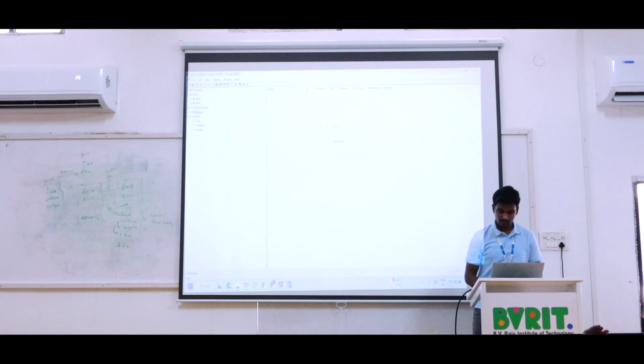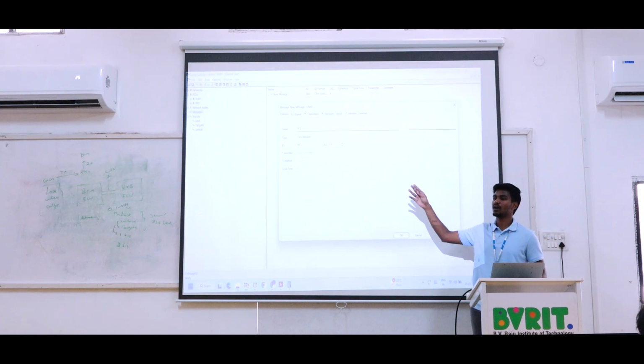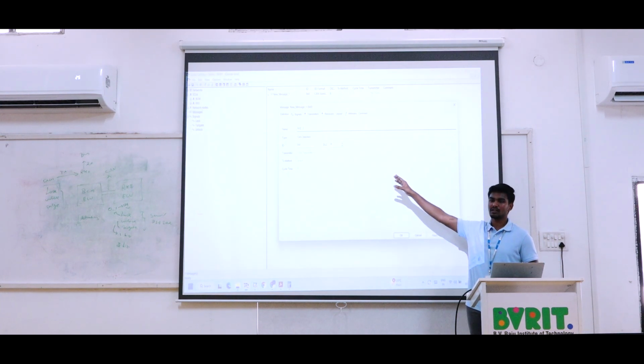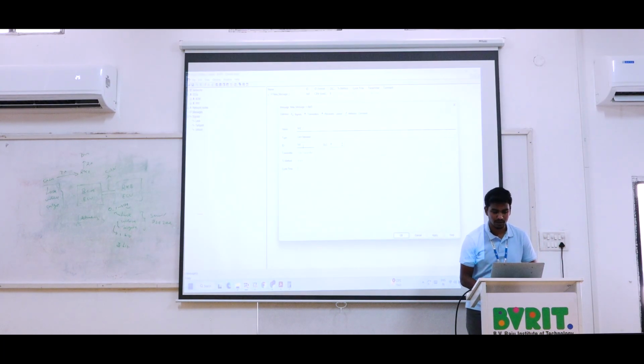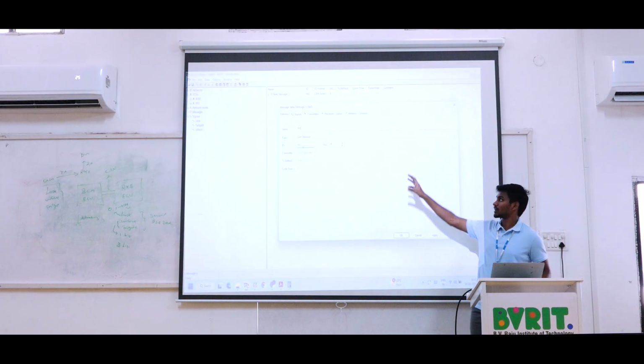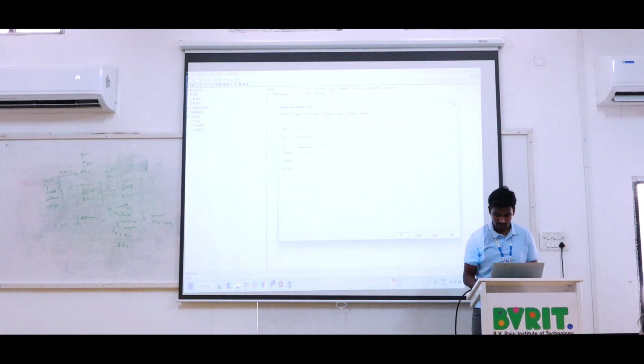So right click, open new. Now we have to get the definition for the messages. Here I can say the message is RKE_1, which means we are going to create the RKE message. But this name is not a specific thing, we can give any name, but the identifier is the important thing. For our confirmation only we are creating the name as RKE1, but we can give anything. The ID number is the main thing, so for the ID number we can use 0x400.